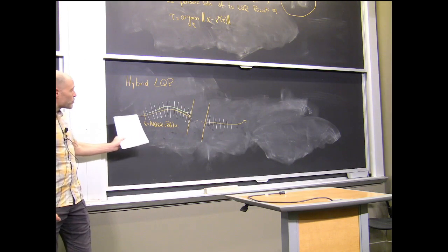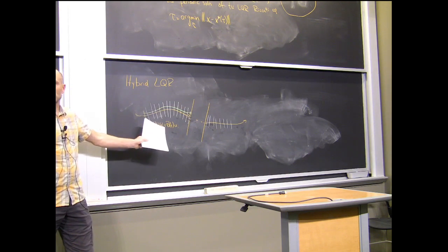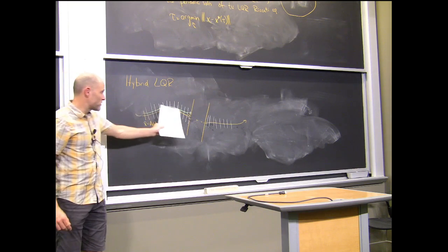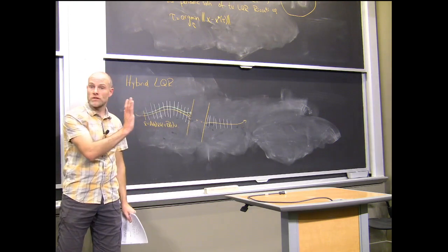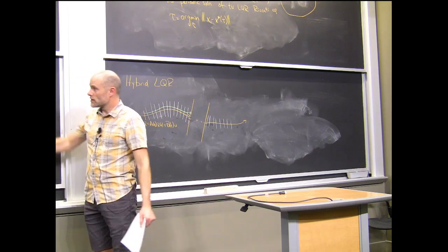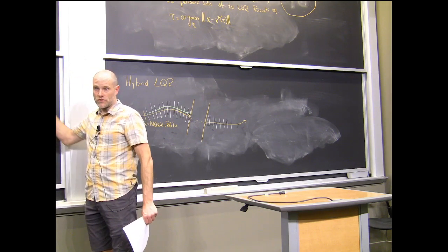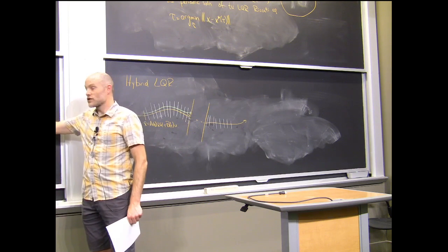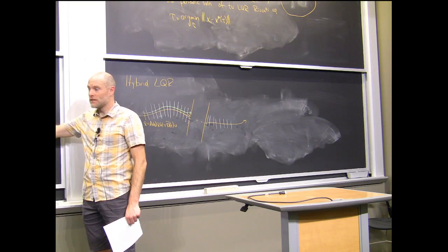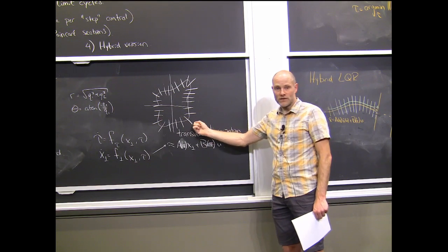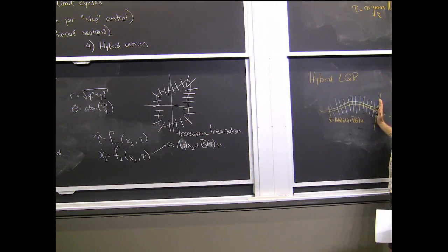Okay, so the transverse LQR is actually exactly the right way to do LQR, hybrid LQR, with the additional construction that you can line up your transverse coordinates with the switching surface. And that is why, like I said at the beginning, doing the construction for limit cycles and doing the construction for hybrid goes sort of wonderfully together. The original construction was motivated by orbital stability. It gave us these transverse maps, transverse coordinates, but it turns out to be exactly what you need to line up with a switching surface.